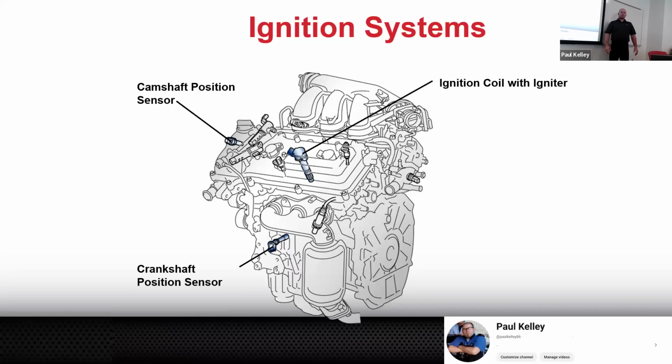So if they've got the budget and you're like, hey, let's just do 6 brand new Denso high quality coils, it might actually save the customer money over time, but you don't know the customer's details, right? You don't know if they're struggling to pay their bills at the end of the month. If they are, I don't think I'd throw 6 coils at it. I think I'd probably do 1 and see how long it lasts. Make sense? So this is where we do a lot of our diagnosis.